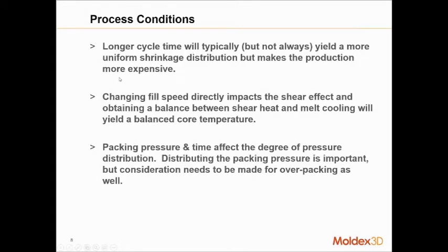The third effect into the warpage calculation is your process conditions. The longer cycle time will typically yield more uniform shrinkage, but also makes your production more expensive. This is something that we should all be aware of. A longer cycle time doesn't necessarily always yield a more uniform shrinkage distribution and ultimately produce less warpage, but I'll say that's the general trend.